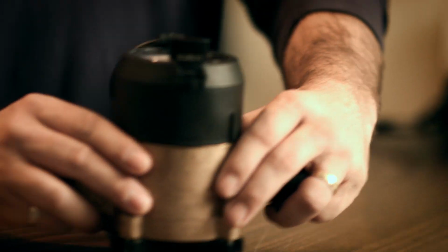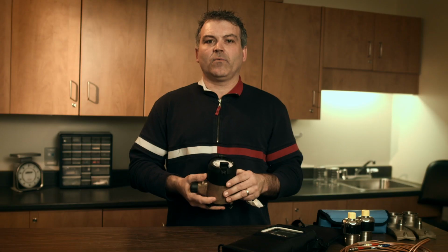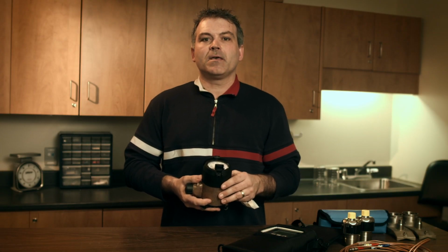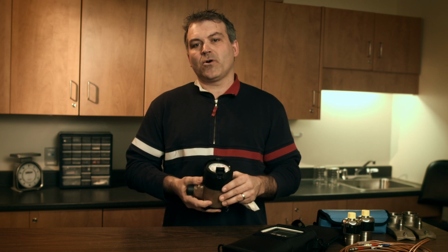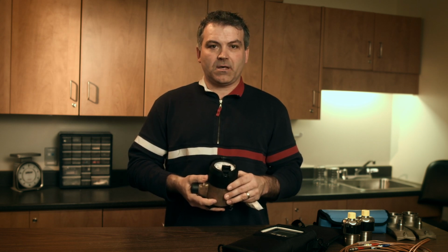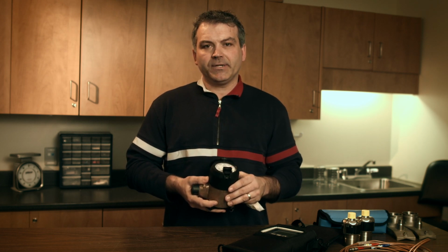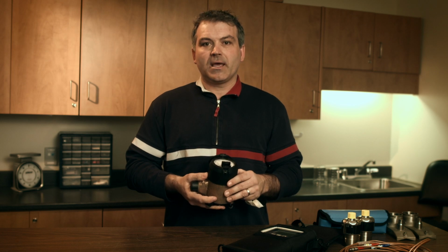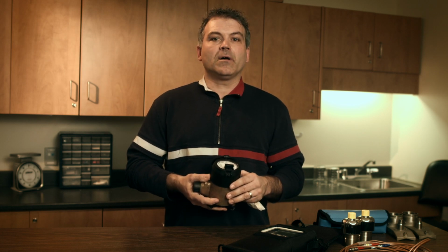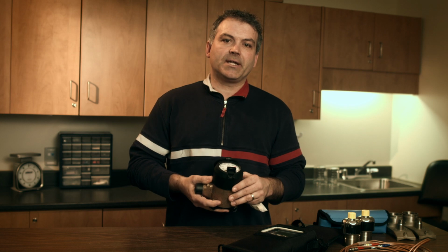Flow meters can also be used to control chemical addition systems such as hyperchlorination systems and gas chlorination systems. In order to measure or calculate the flow rate of water in a distribution system, an operator will need an existing flow meter or to have a flow meter installed. Various types of flow meters are available for use in the water industry, including mechanical types such as paddle wheel and turbine flow meters. There are also electromagnetic and ultrasonic type flow meters.